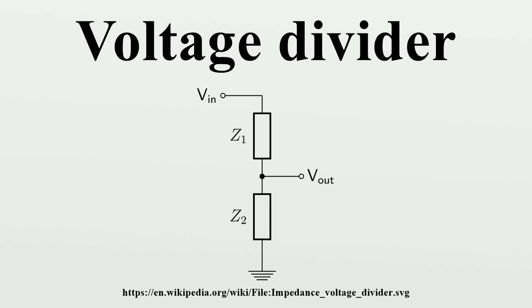Special high-voltage resistors are used in such probes as they must be able to tolerate high input voltages and, to produce accurate results, must have matched temperature coefficients and very low voltage coefficients. Capacitive divider probes are typically used for voltages above 100 kV, as the heat caused by power losses in resistor divider probes at such high voltages could be excessive.